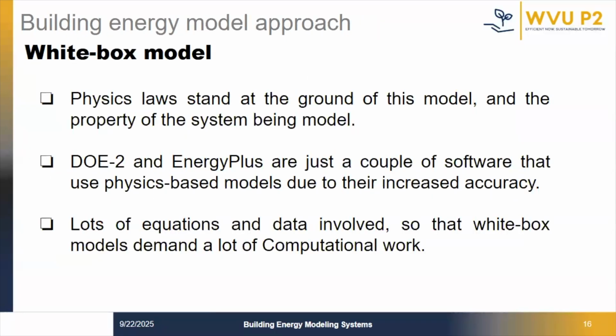Starting with the white box model, white box models are the most rigorous approach which uses fundamental physics laws to simulate every aspect of a building's energy performance. Tools like EnergyPlus and Department of Energy 2 excel here, which offers greater accuracy by modeling heat transfer, airflow, and systems interactions in detail.